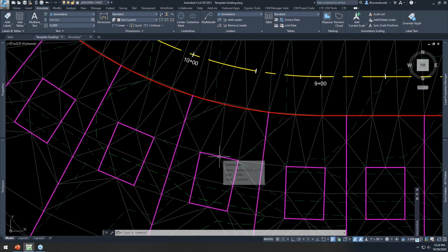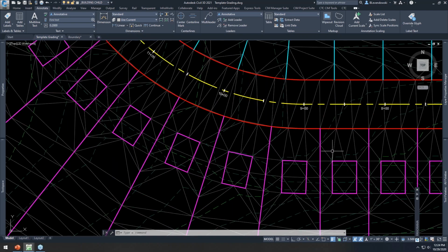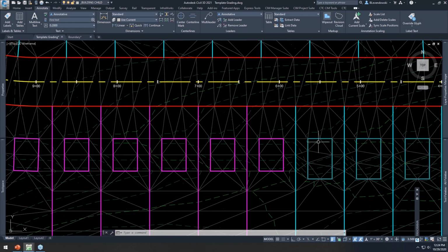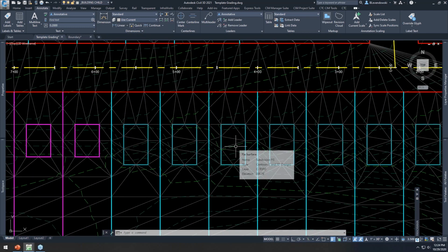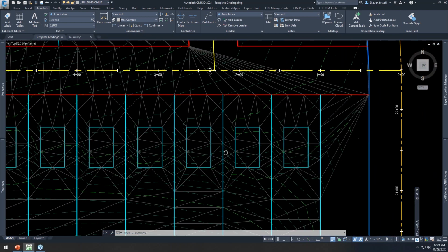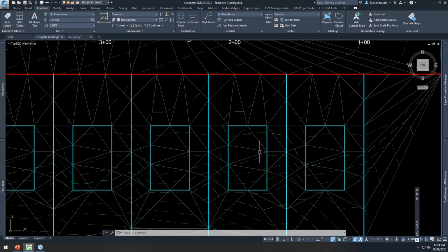and add a 4%. Okay, now that's the way I'm thinking about it. Center of the lot, come up 4% at 40 feet. Obviously, it's going to vary for you. How you think about it will certainly vary, but it's very flexible in that way. What you choose as your base point, okay, it doesn't have to necessarily be the front midpoint of the lot. It could be anywhere on your house pad. It could be a distance away from your house pad. A lot of different ways. I could achieve the exact same result by having picked a base point down here and then specified a relative elevation and told it to be 2 feet above the road, and it would take care of the rest for me.